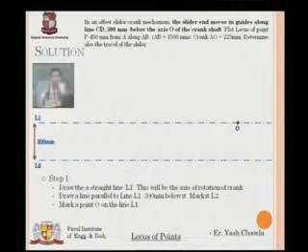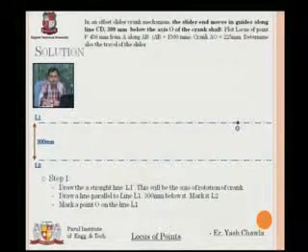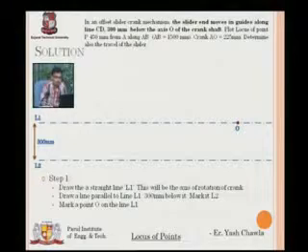The next step is, I'll take a point where my crank is going to rotate. The axis was O, so I mark it as O. This is the center of my crank circle, or the center about which my crank is going to rotate. So I have taken a point O on L1, which is the center of the crank circle.